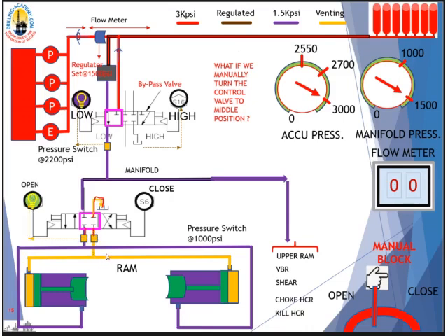On the closed line here, it's still vented. It was vented before and now it's blocked, so it's still vented. It contains the same low pressure. Therefore, it doesn't send any signal to light up the closed light pop here. All right, so that's what happens when you turn the control valve to the middle position.